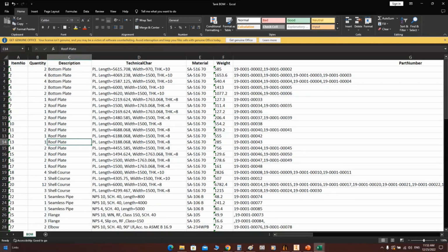Some other companies, for nozzles for example, if you have 2 identical nozzles with the same flanges, same pipe, same reinforcement pad, give each item a separate part number. But SEG deals with identical items. SEG will give the same flanges the same item number, the same pipes the same item number, and the same reinforcement pads the same item number if they are identical.